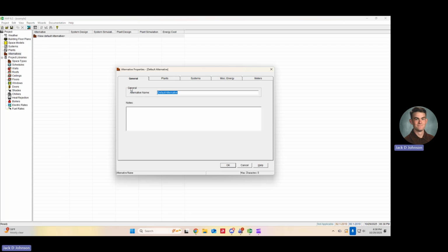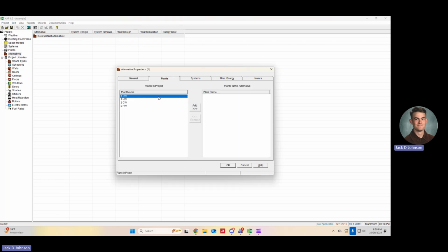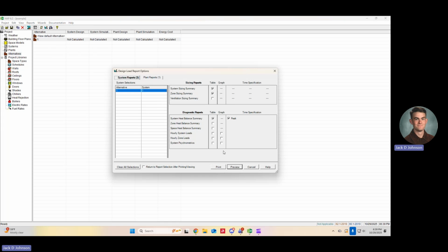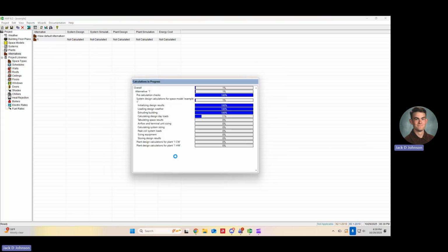All right, then we're going to go to alternative. All right, see if it comes up with an error. Plants, cold water and hot water system. It's already loaded. You're going to click OK. Then you're going to go to the report. You do not need the psychrometric. You can unclick that. This takes a minute, and it's fine. Oh, no errors. All right. Whenever you get errors, there's going to be a description, and it's going to tell you basically how to fix it.